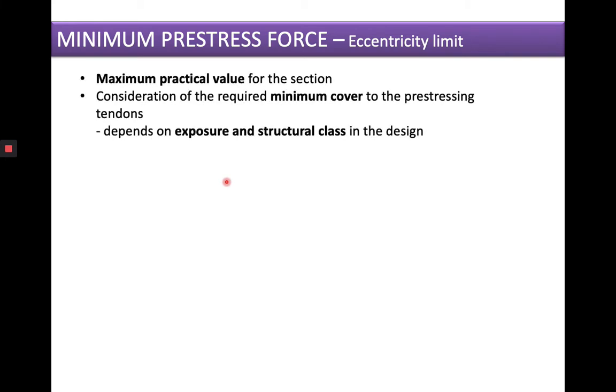I will proceed with the lecture for today, which is for the minimum pre-stress force in consideration of the eccentricity limit. Right, so we can see here we have the maximum practical value for the section. So we need to determine this based on the eccentricity limit. It is in consideration of the required minimum cover to the pre-stressing tendon.